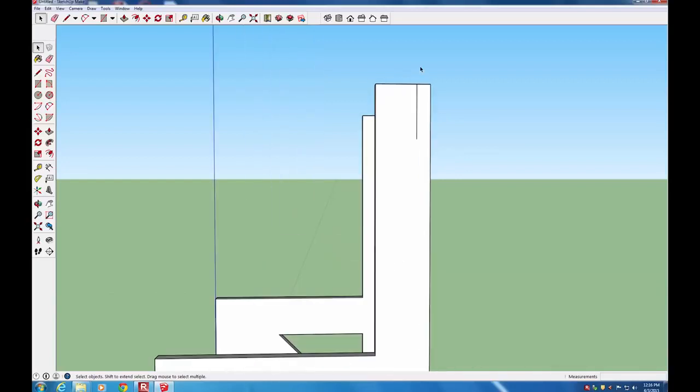So I'm going to zoom in up at the top where our first one's going to be, select the rectangle tool from the large tool set. I'm going to start drawing from this corner of the line and draw it down. And we're going to type in 0.1, 0.05. That's going to make the correct size rectangle here.